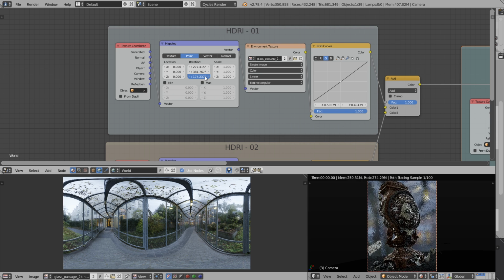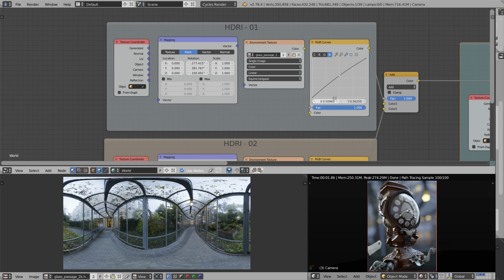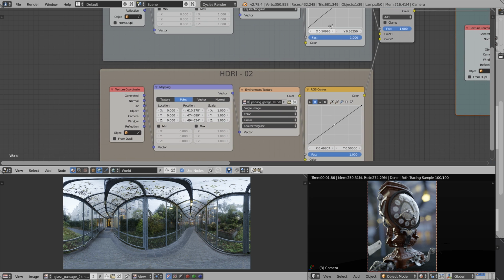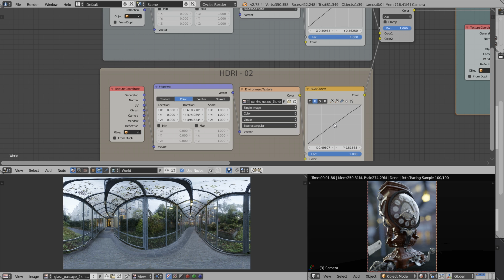And what I'm doing, I'm still searching for the best angle for lighting. I'm still not sure that what we see is the best that we can get. So I'm trying to tweak here and there some things. For example, what I'm trying to do here is tweak the second HDRI to make it a little bit warmer. In other words, to create a little bit of a complementary contrast going on between the cool tone of the first environment and a slightly hotter look of the second one.